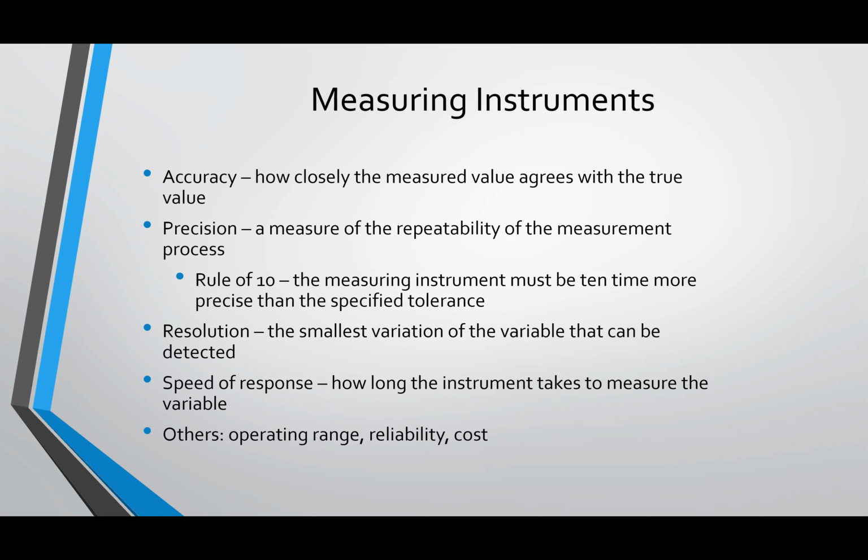Another factor would be like temperature. So in pharmaceutical manufacturing, for our pediatric formulas, they were all liquids. And so we had to measure different temperatures, and we used digital thermometers that gave us temperatures in Fahrenheit and Celsius ratings to the hundredths place, and it was pretty much instantaneous. And so for production capabilities, you want measurements to be done pretty much instantaneously. If you are doing measurements offline by hand, the speed of the measurement is usually the speed of the operator. So then reliability, cost of the device all become factors as well.